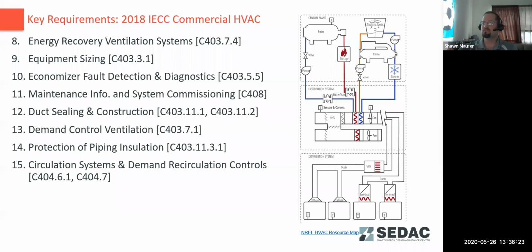Where can we find data for fenestration updated code requirements, since they seem to have become far more rigorous? The IECC tables list U factor, solar heat gain coefficient requirements, as does the ASHRAE 90.1, and also air leakage requirements for window assemblies. As far as testing procedures, there is another table that lists acceptable testing procedures, including the NFRC 400 testing requirements. So depending on whether it's a door, window assembly, a pre-manufactured window, there are a couple of different testing requirements to achieve those, but they are all listed in the 2018 IECC and in ASHRAE 90.1.